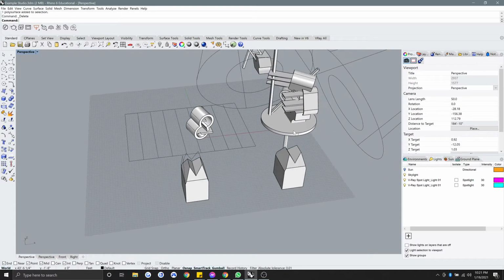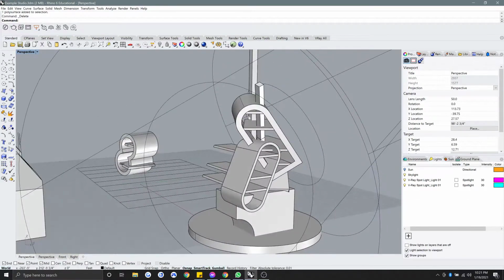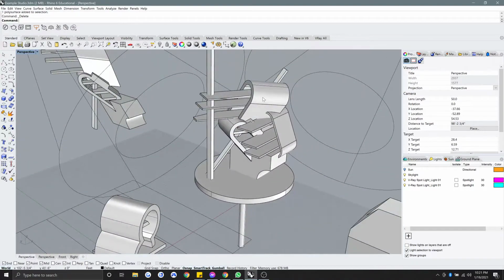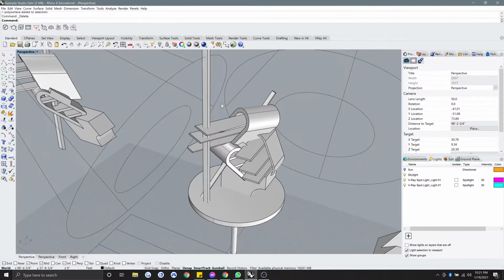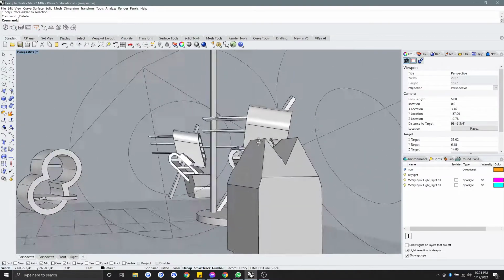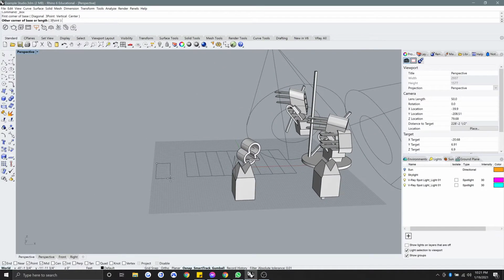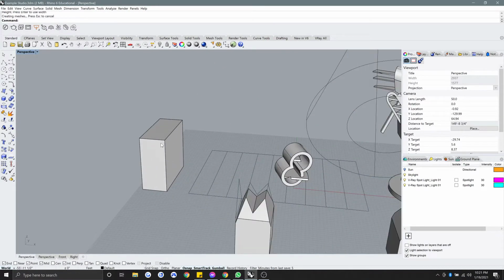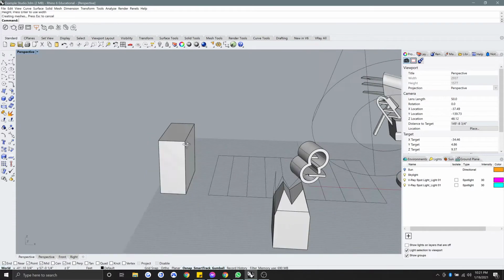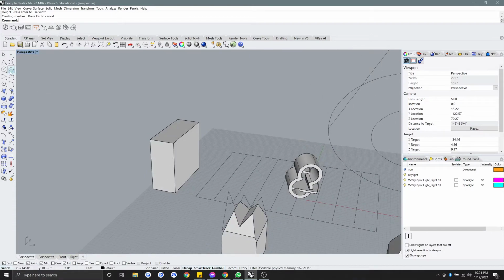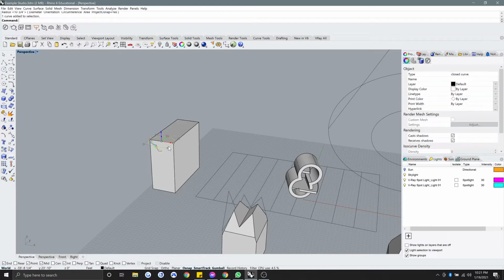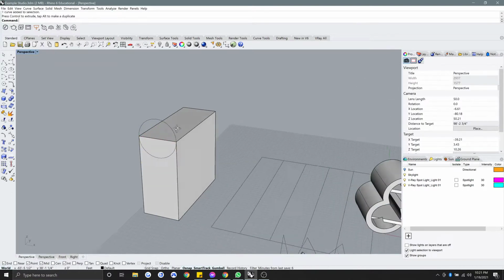And so I'll start with something like this, or similar to this, but if my drawing was a negotiation of these semicircular end forms, stacked and addressed, and then maybe some vertical supports, maybe some horizontal supports and floor plates, what I might do is start by first using a box and giving myself something to carve with. My options, if I want to add a semicircle to this, are carving off these corners, that's just using the circle, and then using the gumball, which is down here, to turn the circle one direction.